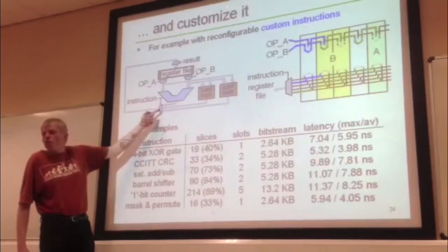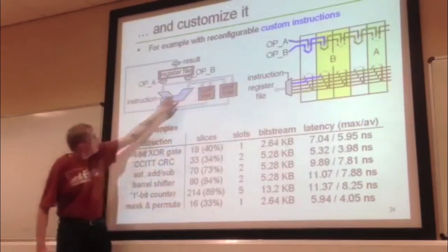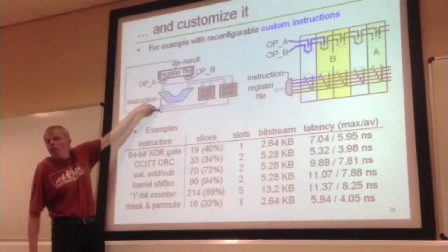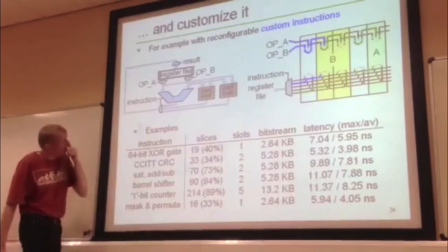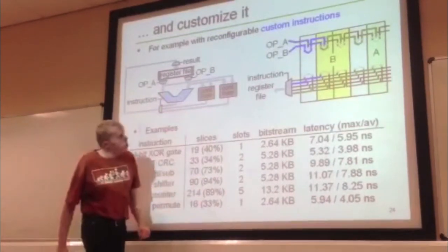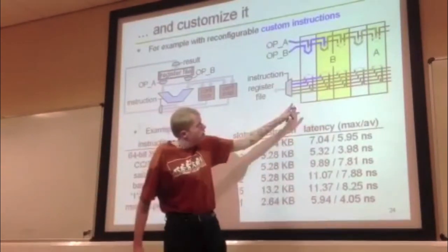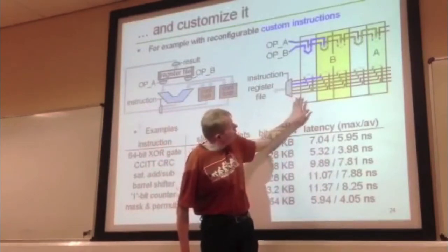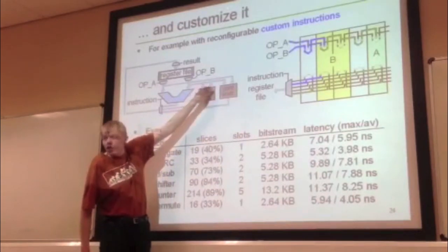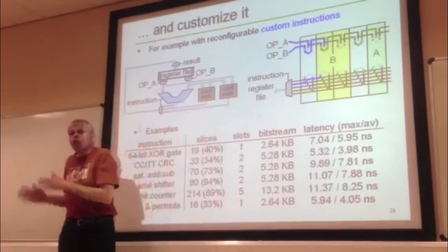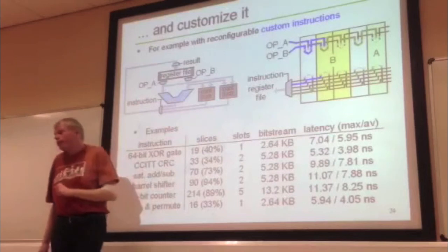Yeah, and to use this is relatively easy. You simply access the two operands, put this to your own hardware module, and depending on the instruction, you use simply a multiplexer to select your own instruction. It's that easy. And that's not the only thing you can do. You can imagine, and that's what I did, that you exchange these blocks. So depending on which program you currently execute, you can even execute or start different customized instructions.